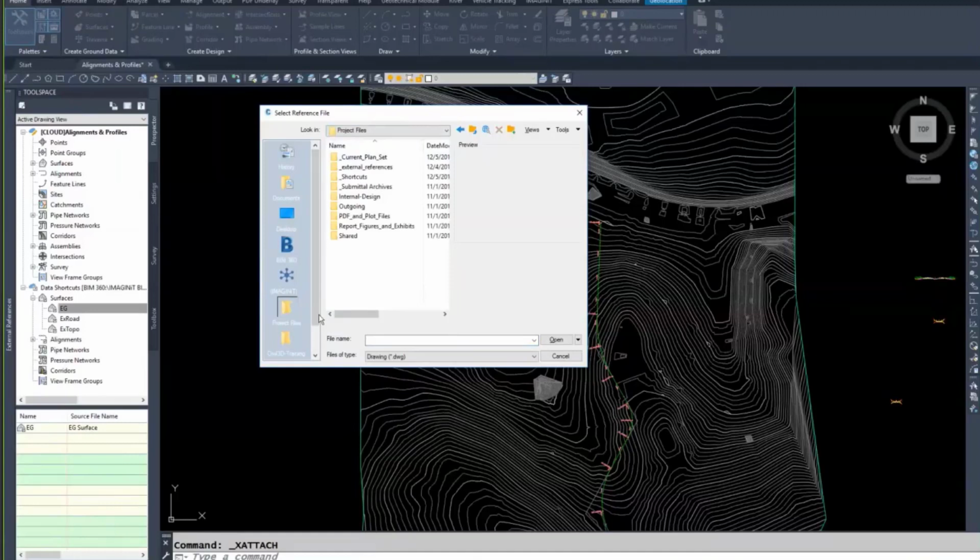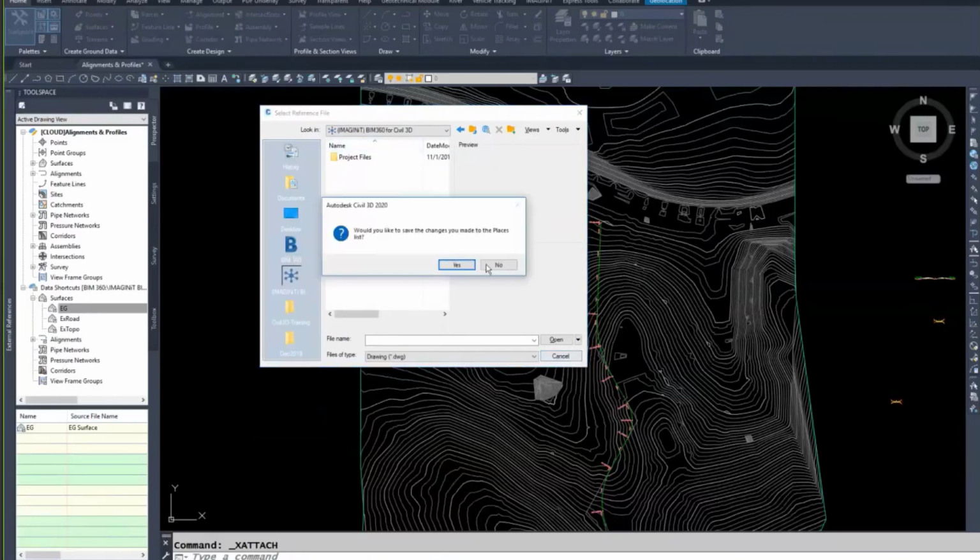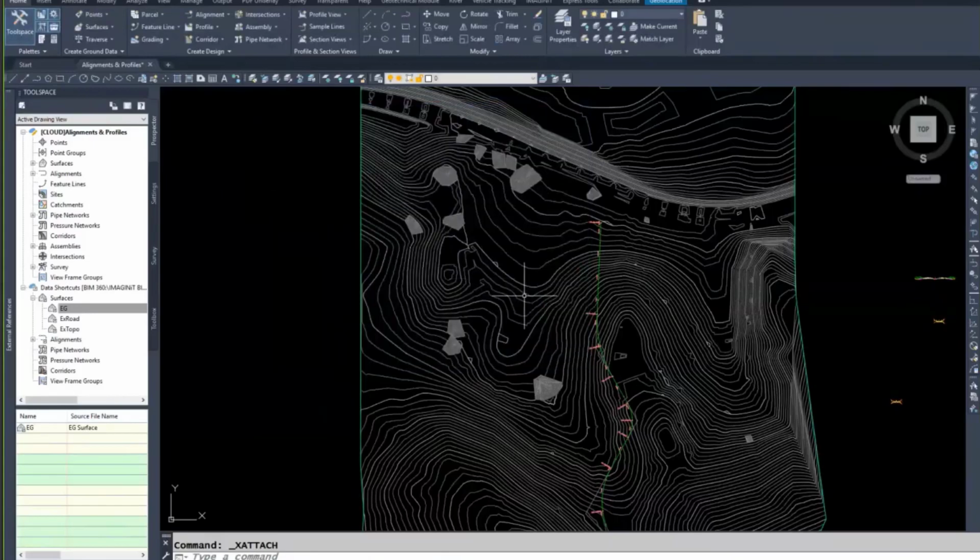And you can see that it is actually syncing to my BIM 360 local cache folder as well. So although it is linking me to BIM 360 there, it is giving me this path within my local drive through that desktop connector. So the desktop connector is actually what's driving the connection between the BIM 360 hub and the drive that I'm working on or referencing here within Civil 3D. When I try to make a change or save a file, it's also going to run through the desktop connector. The desktop connector itself is a service that runs in the background.